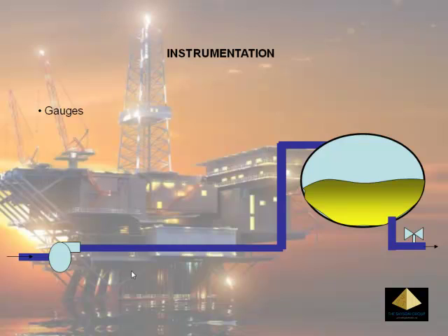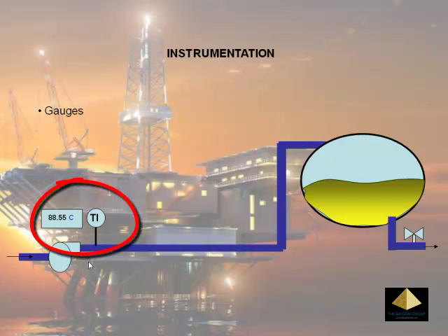And then instrumentation will be introduced to the process. Instrumentation is actually the measuring instrument that will measure the characteristics of the process. One very common characteristic that is measured in a process is the temperature. So a temperature transducer will be installed and a temperature indicator or a temperature gauge, where the operator will actually come to the field and make a record of the temperature gauge.